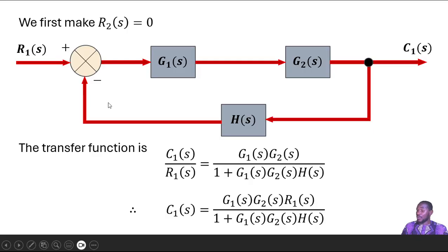Okay. Now, this is a feedback system. We're going to use the same form as we had before. The forward loop transfer function is what stays as the numerator, because we have these two in series. This one acts on what's coming into it, and this one acts on what comes out of that, so the overall effect is just multiplying these two together.